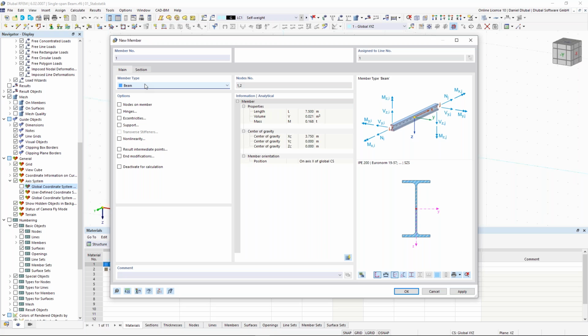In order to consider also the pseudo stiffness in the first phases of your study, I refer to the member type definable stiffness. So we create a kind of fake or pseudo stiffness.